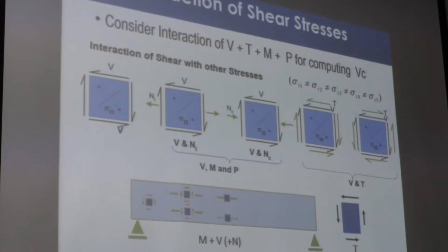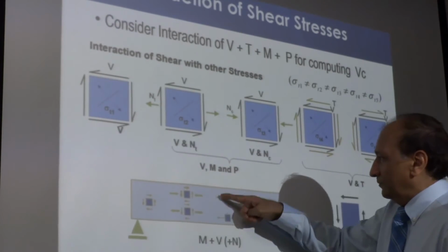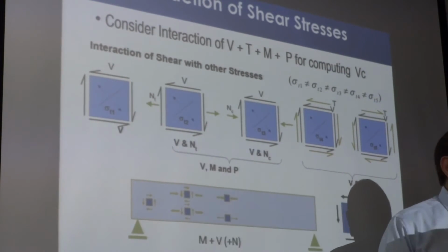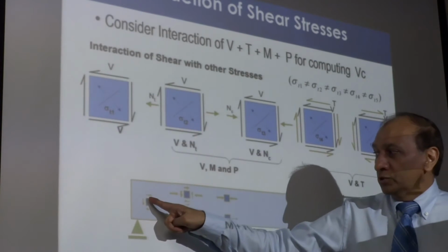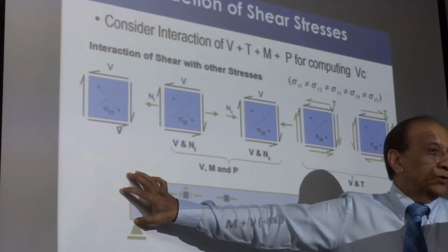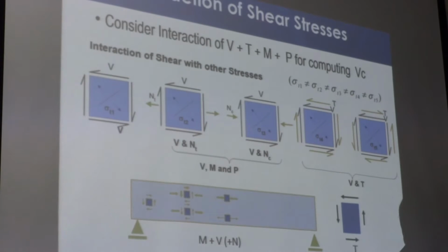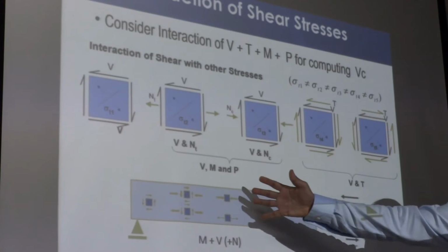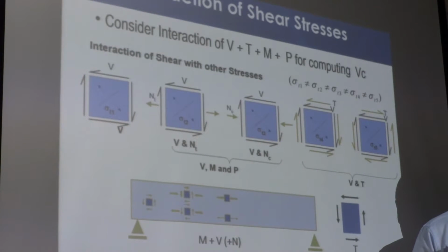Any questions? Do you understand the whole stress state in a member right now? And variation along the length. And this is a simple beam. What if we have a negative moment and then positive moment and some point loads coming here? Then this is not pure shear. This is also a lot of negative moment, which also has tension and compression. So the support is no longer pure shear. Pure shear disappears, right? So bending moment diagram, bending moment variation will also affect this concept.